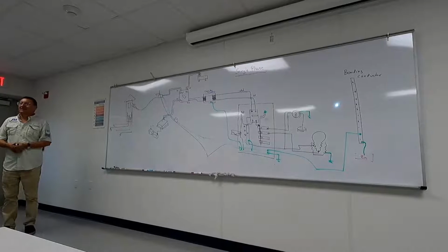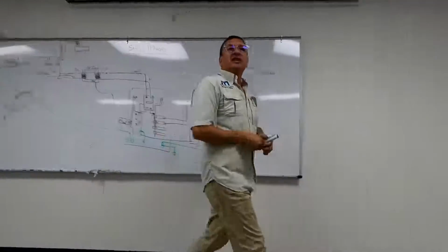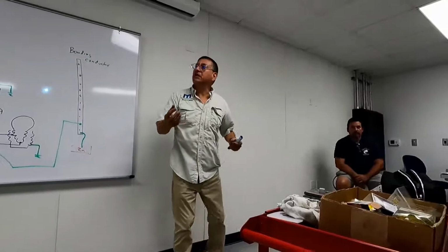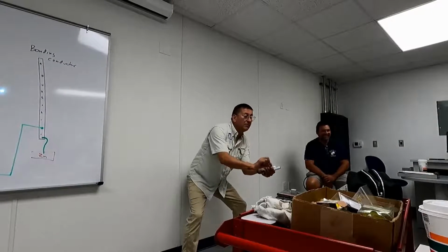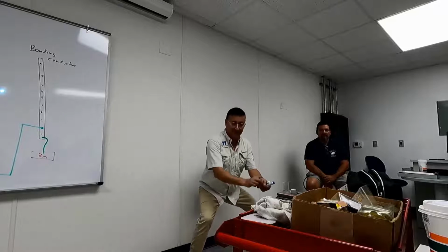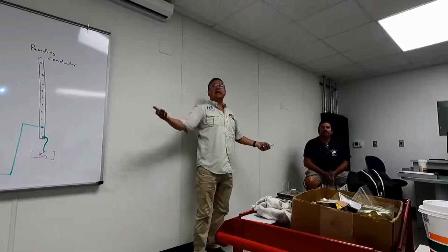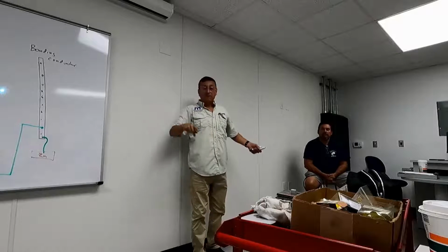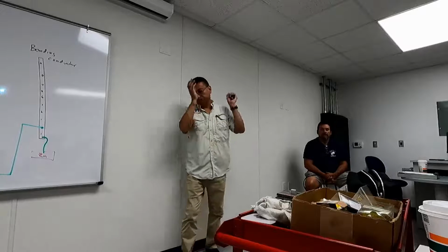It's a ticking time bomb. Danny, suppose that yesterday, another Mickey Mouse technician decided to install the bilge pump. The negative of the bilge pump, oh, that metallic conductor, oh, it's ground. Nice, I have ground here. Positive bilge pump connected, and suddenly I have reverse polarity. I have 120 in the negative. What happened with the bilge pump? Boom. All right. Kaboom.